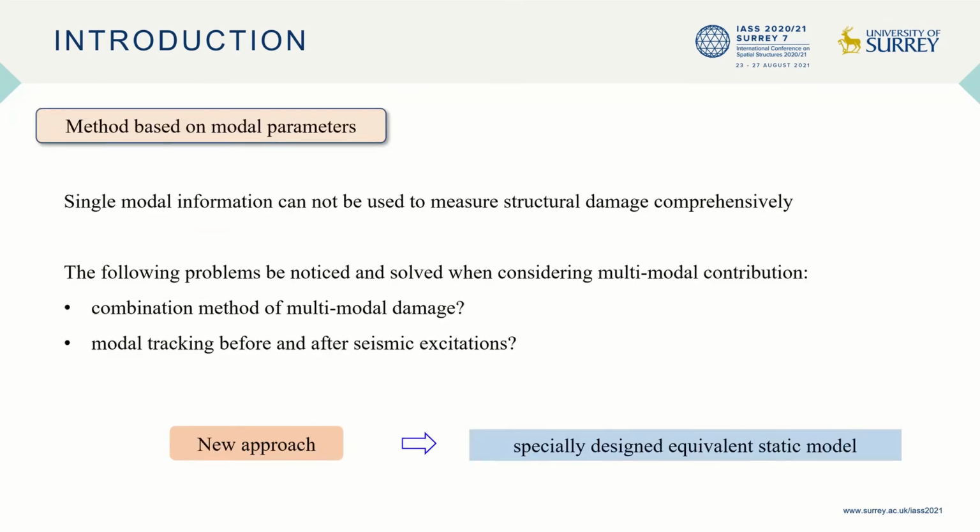Generally, the contribution of each mode response to the seismic response of spatial structures is scattered and relatively uniform, which is different from multi-story or high-rise structures whose seismic response is low-order mode controlled. Therefore, single modal information cannot be used to measure structural damage comprehensively. However, when considering multi-modal contributions, there are some problems, as listed, that have not been well solved in the existing methods, which makes the damage assessment method based on modal parameters unable to be directly applied.